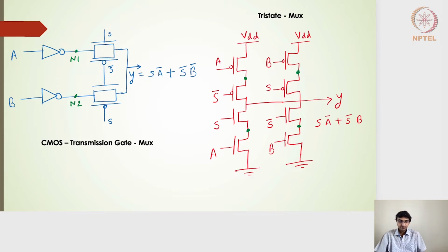Moving ahead, this is the transmission gate configured multiplexer circuit, and it's a 2:1 multiplexer. I have represented it in a very simple manner. Let's say when S is 1, when the select line is 1, I will have this transmission gate passing the input to the output Y.